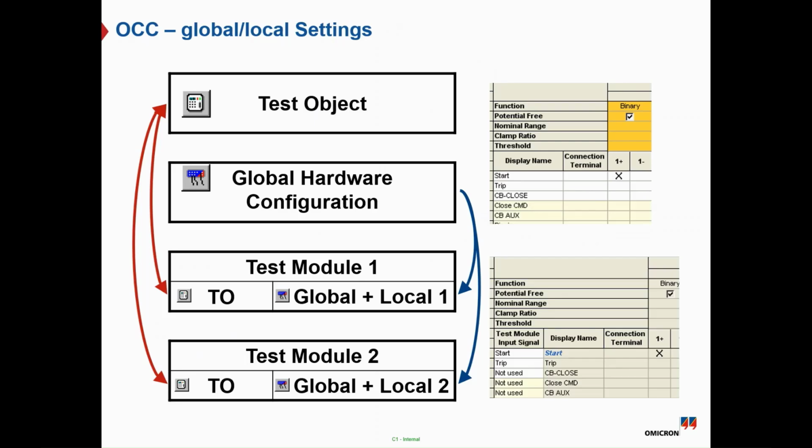So once you are importing another relay parameter setting, it will automatically change the values inside your customized test plan or inside your OCC file. So no need to start from scratch with a blank sheet of paper. You can export and import the relay parameter setting inside the OCC, and it will be reflected and auto adjusted to the